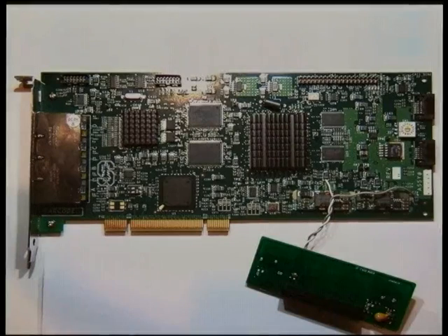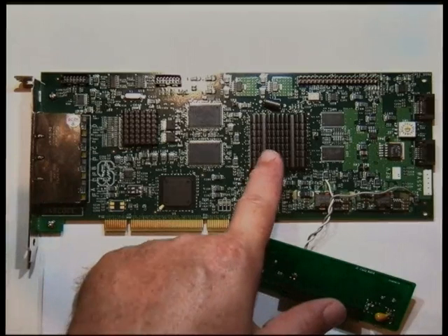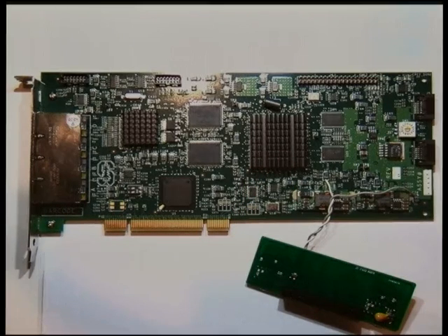There are 2 platforms that are currently being used. The NetFPGA 1G, which uses the Xilinx Virtex 2 Pro 50 FPGA, which has been deprecated by Xilinx some time ago. And that's what I've got here. So this is a NetFPGA 1G. There are 4 1G network ports over here. The Virtex 2 Pro FPGA underneath there. There's another FPGA just here, which is used for the PCI interface, also a Xilinx device.